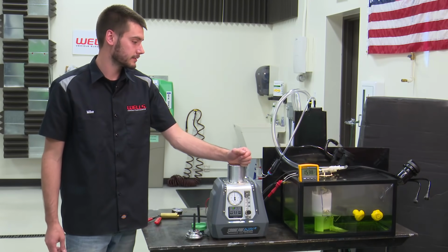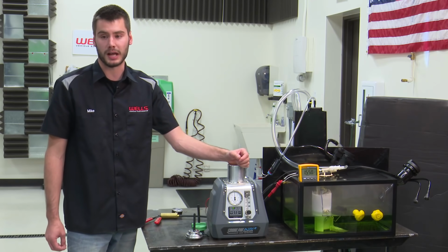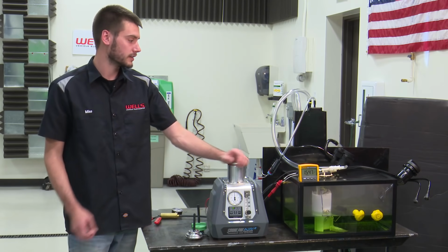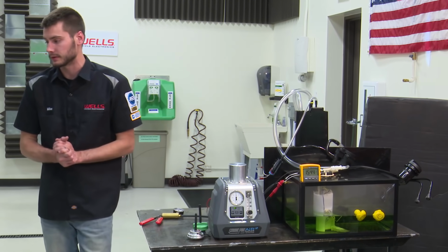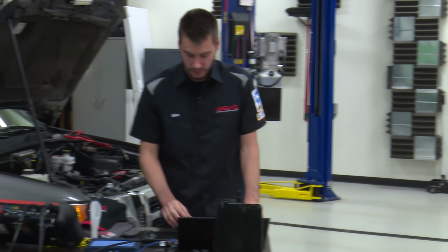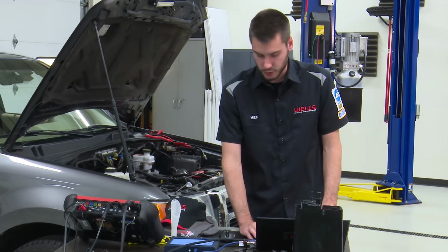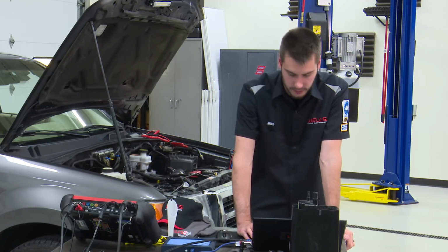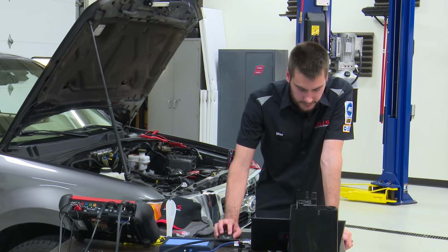So, all right, that is that vent check. It's going to check for the blockage in that system by watching the bleed up time after the vent is open. All right. Let's go back over here. Got a couple more things I want to cover before we whip out the lab scope and the scan tool and get to the vehicle. I know that's what you guys are waiting for, the fun stuff, right?